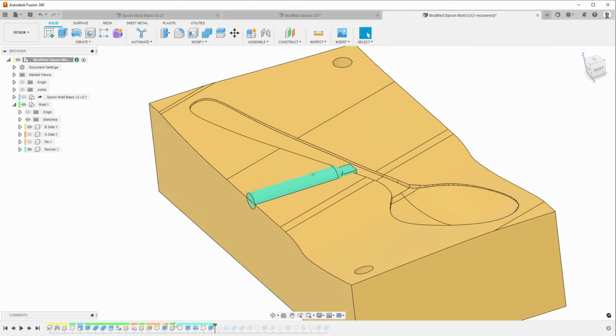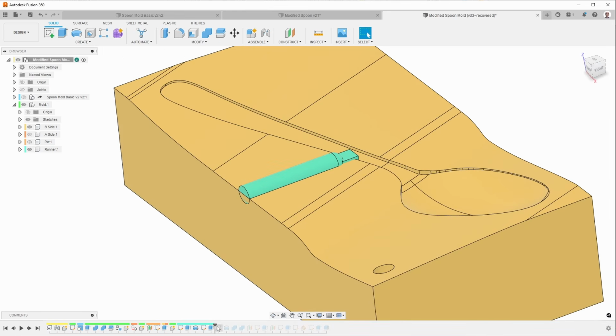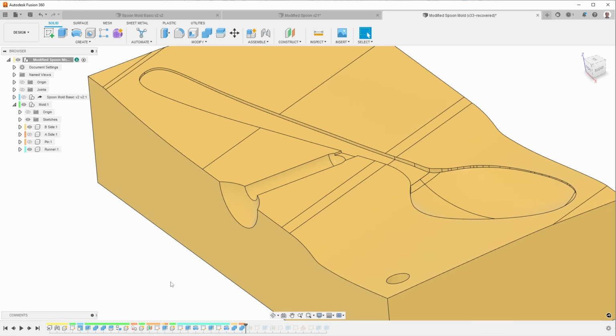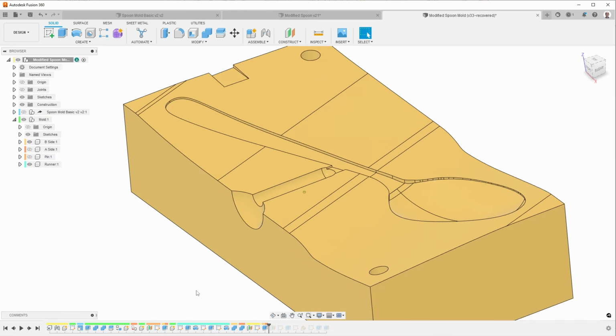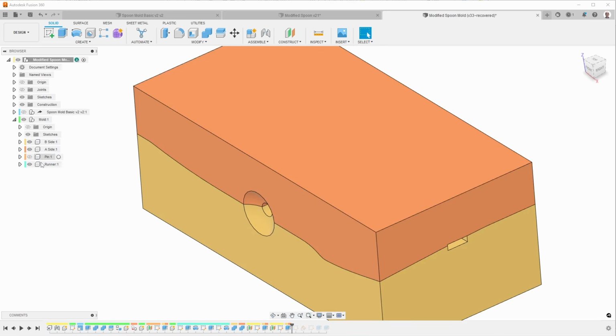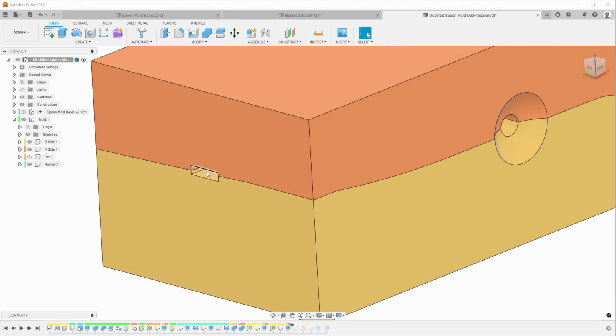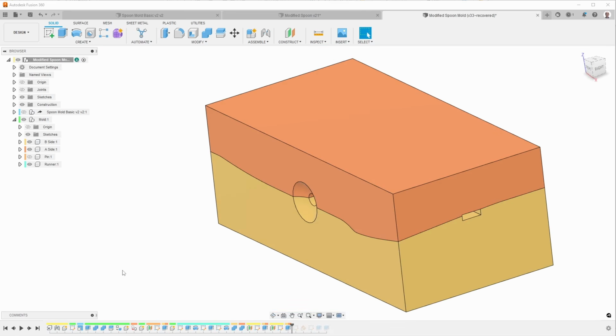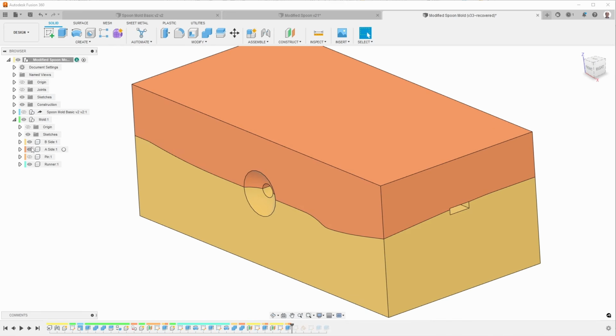And then I added the sprue to bring plastic in. And then this next part is because the nozzle has a radius on it, so we want the nozzle to seat very well. And then what I do is I basically subtract these from the mold itself, and now you can see the seating area for the nozzle. Next thing is I added a couple slots, both here and there. These slots are for a screwdriver that allow you to, let me show it this way. So you put the screwdriver in here and twist one screwdriver on each side, and that makes it easy to pry the mold halves apart.